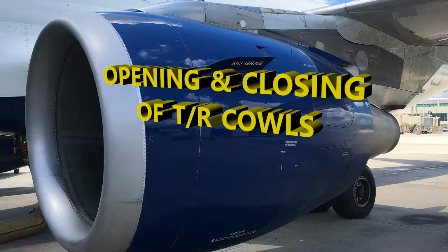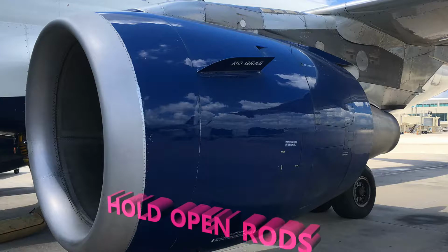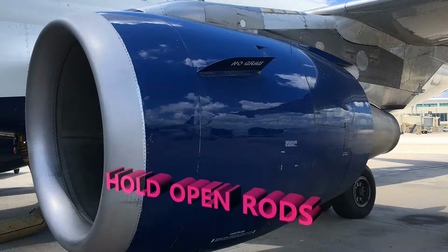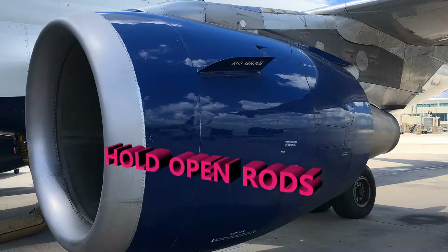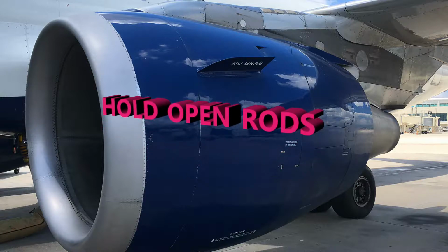And there are different degrees of open position or over travel position, etc. Obviously the stowed position is completely closed. All right, but that's what you have with that. Again, just follow the sequence at your MRO from the actual aircraft maintenance manual. Your hold open rods, I mentioned before, are just making sure that the fan cowls are secure when they're open, when you're doing maintenance in there.